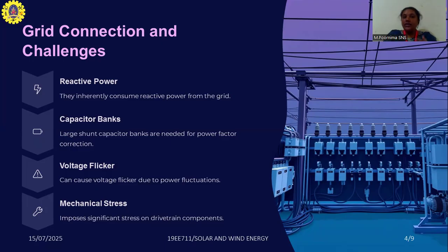This is indirectly a big challenge for connecting to the grid. And the mechanical stresses: it imposes significant stress on drivetrain components. This is one important challenge. These are the list of challenges while connecting to the grid: reactive power, the capacitor bank, voltage flicker and mechanical stress.